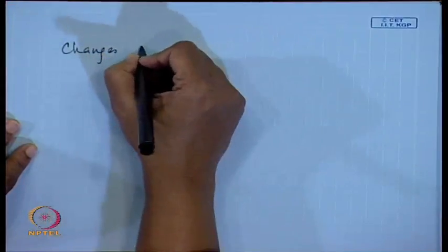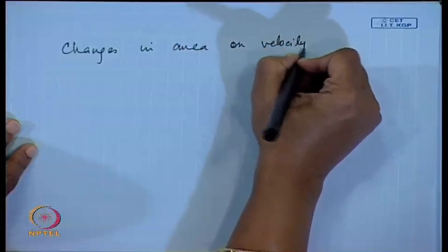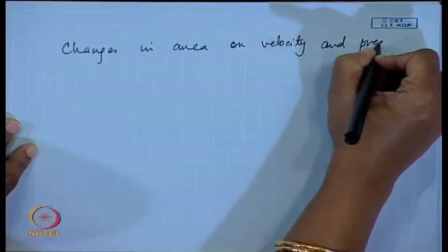We will be starting from the energy equation, the final form that we had derived in the last class, from where we got that the enthalpy head and the kinetic energy head remain constant for an adiabatic isentropic situation. So, from there we will start and see how area changes affect the compressible flow cases. Actually, an area change changes the velocity and it changes the pressure